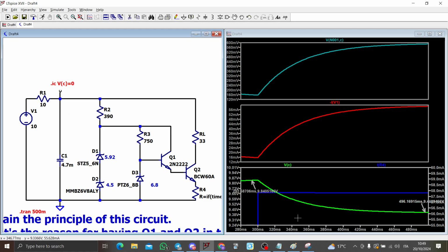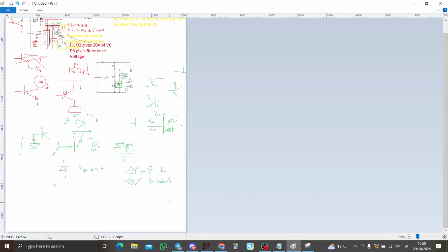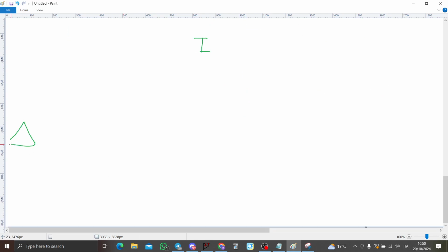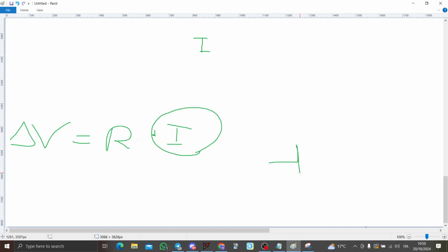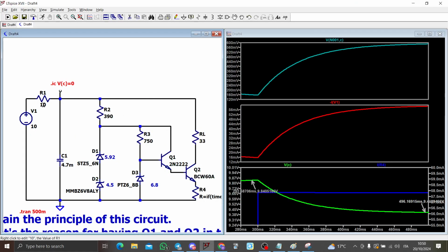So if you put a lower resistor, the drop voltage will decrease as well, because in the equation delta V equal to R times I, I is decided by the load of the last transistor here, the RL here. So the load is decided by this guy here, and the R is kept constant. So meaning that if you change R to 1, you will...